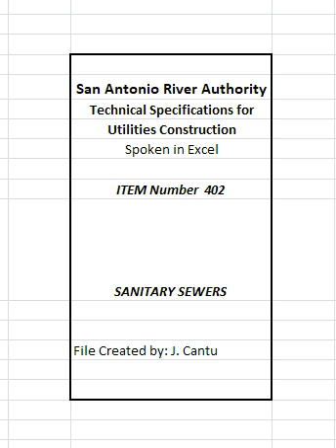7. Cast iron pipe. Cast iron pipe will not be permitted for use as sanitary sewer transmission line. 8. Ductile iron pipe and fittings. Ductile iron pipe shall have 60,000 psi tensile strength, 42,000 psi yield strength, 10% maximum elongation and shall conform to the requirements of the latest revision of ANSI Standard